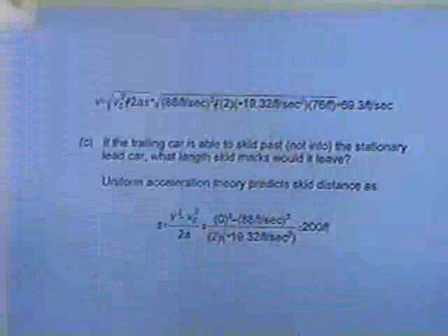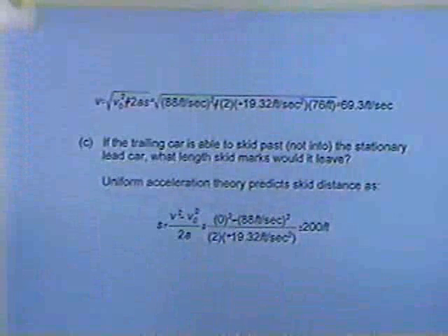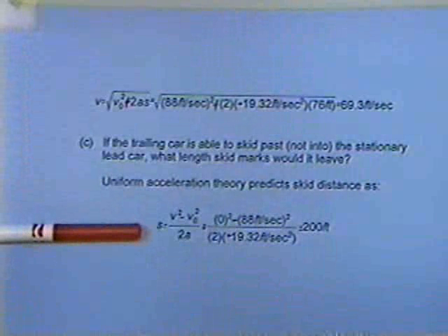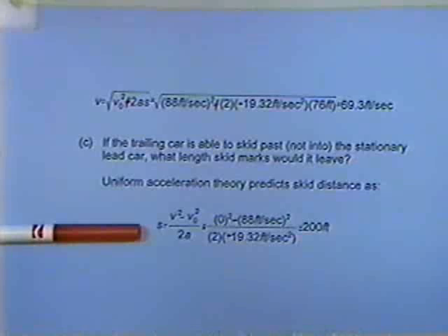So again, if I go back to your notes there, we need to put a couple of negative signs, one minus sign and one negative sign, in that formula, and we would come up with a skidding distance of 200 feet if the vehicle simply skidded to a stop once the brakes were applied on a pavement whose friction was 0.6.